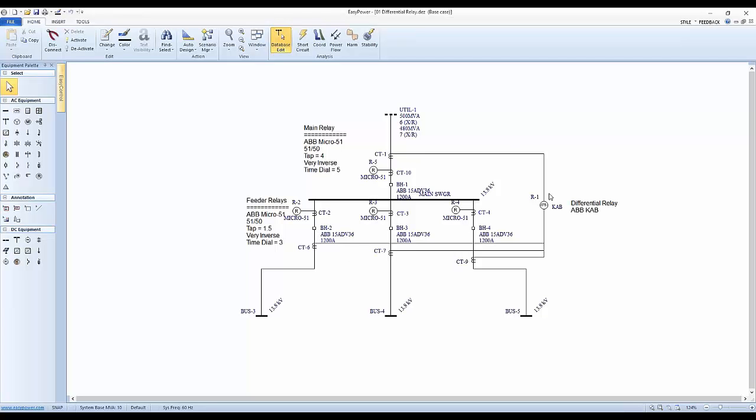So the purpose of a differential relay is to protect a specific piece of gear like a transformer, a major transformer, or in this case the switchgear. Rather than look at any single circuit, it will, in effect, null out the standard currents for the system that are normal. It depends upon the way the CTs are connected, and in some cases the way the relay is connected.